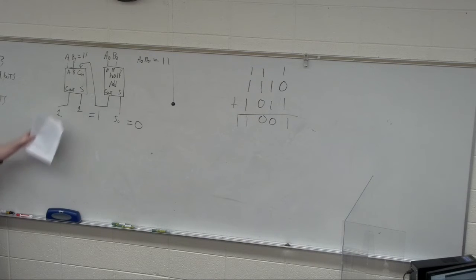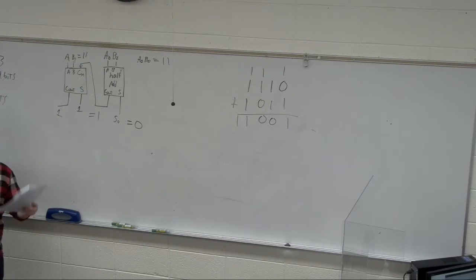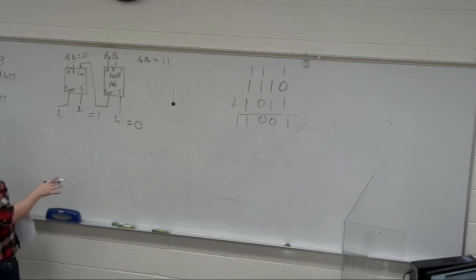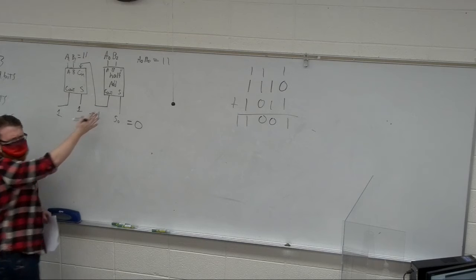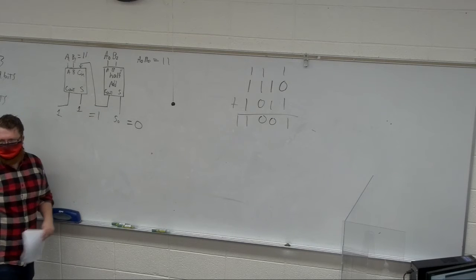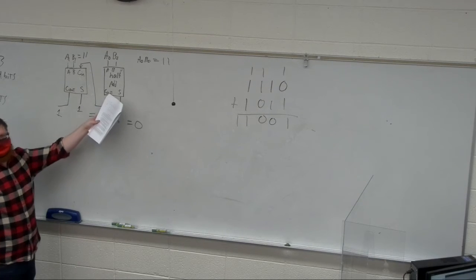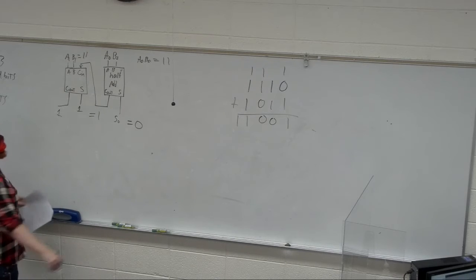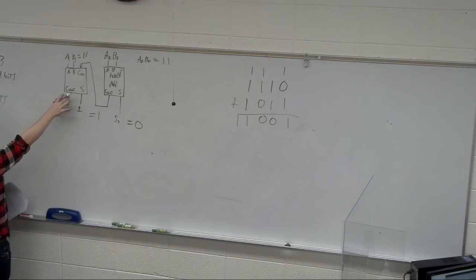Do you believe me when I say I can just string more and more of these together? Yes. Right? So that's how we build an n-bit ripple adder. We can just make this as big as we need to. Now this is actually pretty slow. This is an awful adder, but they're easy to understand. Because it's just, I build a half adder or a full adder where I just set the carry into 0, right? There's no even real reason to design a half adder without that. Then I design a full adder, and then I just copy and paste it a million times.